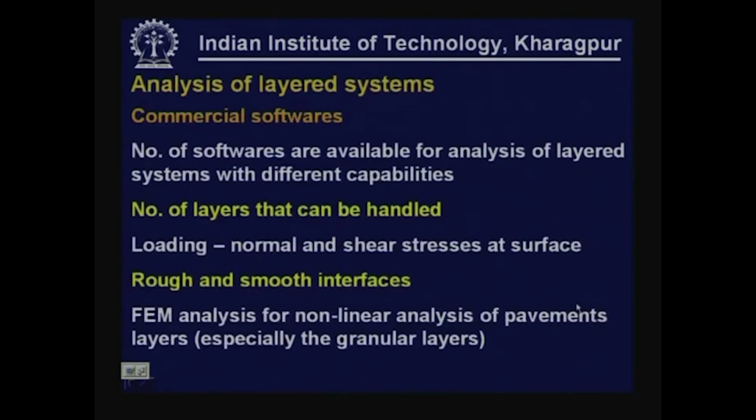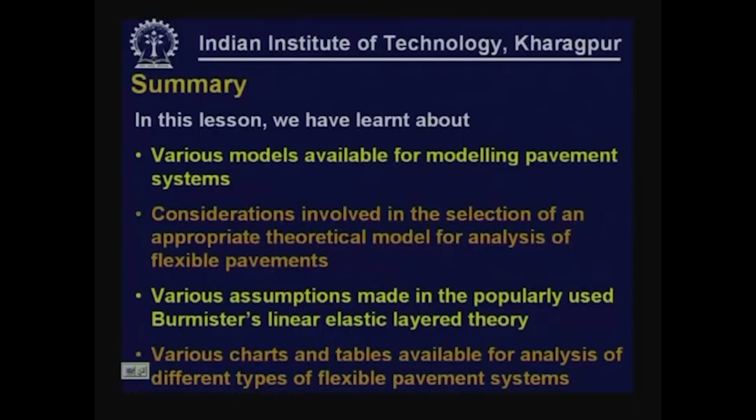There are various softwares available for analysis of multiple layered systems. Number of commercial softwares are available. These softwares can normally handle various layers, different number of layers can be handled. The loading also can be normal stresses, shear stresses at the surface can be considered. These softwares can normally handle rough and smooth interfaces, and there are finite element based softwares also available, which are capable of handling nonlinear behavior of different pavement materials, especially the behavior of granular materials.